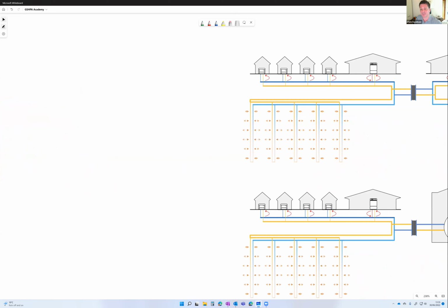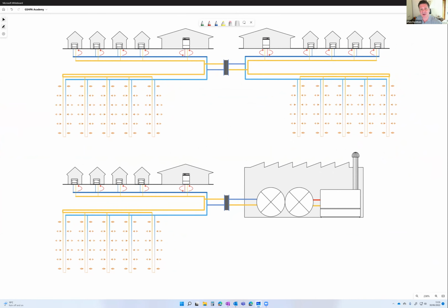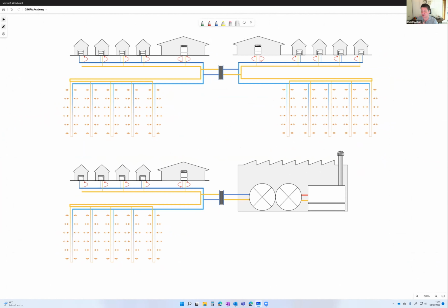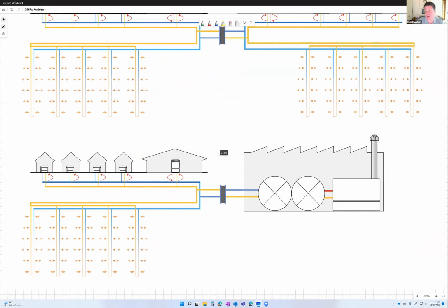But again, you can go further. You can start to connect up not just those ambient heat networks, but other sources of heat into it. I touched on solar earlier on, but you could also connect, say, a 3rd generation or 4th generation heat network in. A common problem in those previous generation heat networks is higher than ideal return temperatures, so you could potentially dump some of that excess heat into your 5th generation heat network. So lots of flexibility, lots of opportunity to take advantage of these as a cornerstone, if you like, of decarbonising and generating more networked systems, more heat networks.